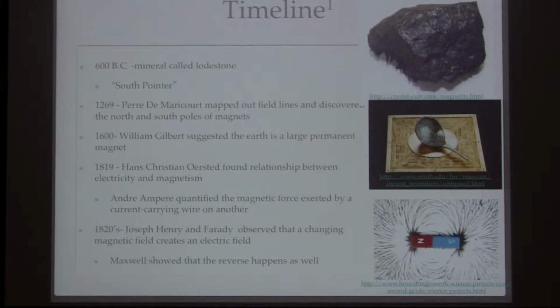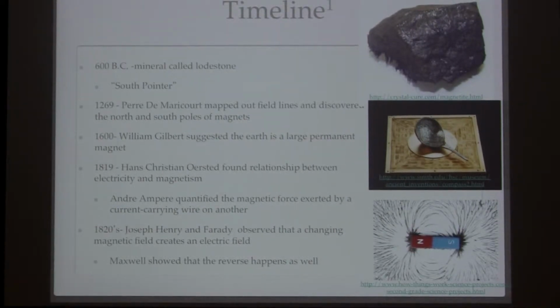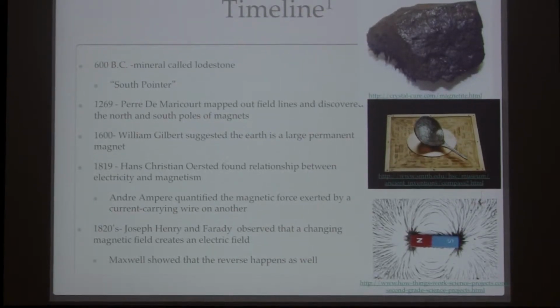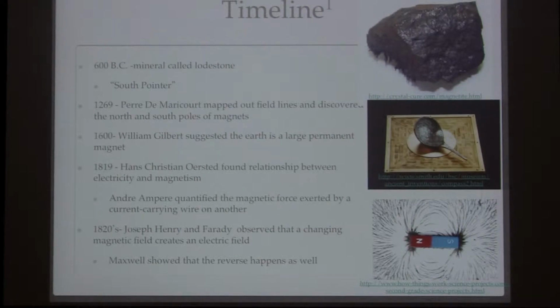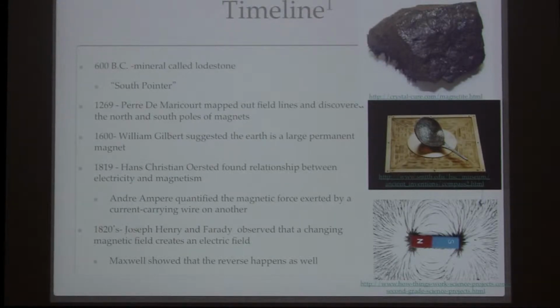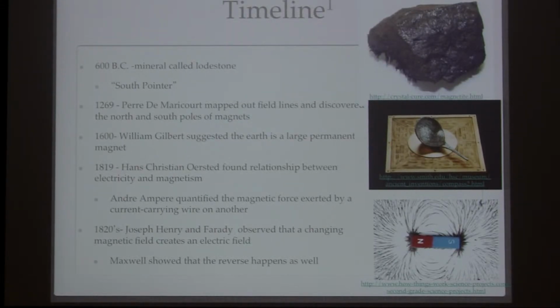I always think about the little sensors on the stoplights. It's basically a coil, and they're measuring the change of inductance as a car drives over it. I was out biking yesterday, sitting at this light, and I'm like, crap, my bike does not have enough metal in it to actually trigger the sensor. But a big heavy car that's full of steel will go over the coil and cause a change in current and voltage, because of the very slight magnetic field that coil is generating. I always laugh, people try and stomp on those things. They think it's weight induced. It's kind of silly. That'd be a big pain, to build a big scale at every stoplight. Anyway, Maxwell's equations show that the reverse happens too, which is kind of neat.